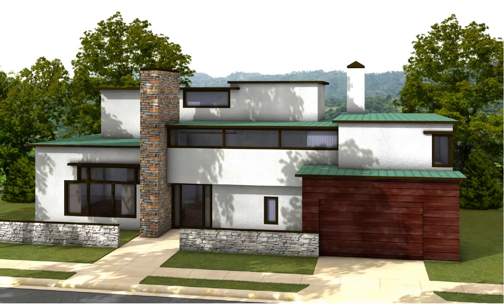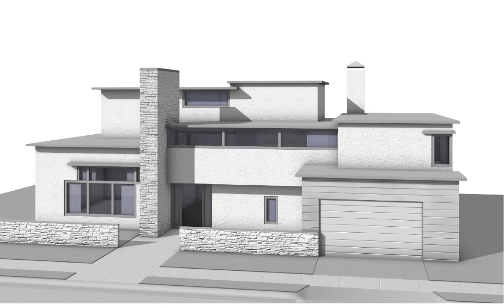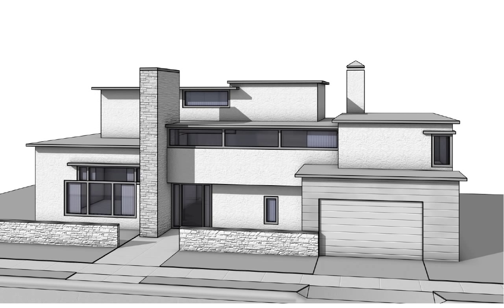Now, sometimes, as we said, maybe you don't want a photorealistic rendering. Maybe you want something a little more abstract. Well, we can do things such as render with just shades of white and use just the bump shader effect. So you can see we can actually render it and have bump shaders for the stone and the stucco patterns and the wood grain patterns and things like that. We can mix and match different types of rendering effects, like we can do just the flat shades without color, but use the bump shaders and turn the show wires on, so we can actually render the wireframe information. And this is all done with a single rendering pass.